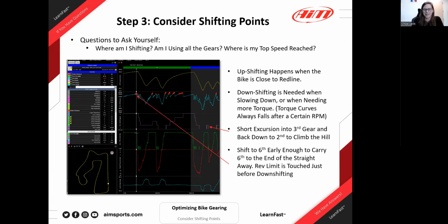And that's a cool preview of where we're going to talk at some point with the math channels. Now RS3 has the ability to have lookup tables. So I use the lookup tables, and the lookup tables know which gear you're in. It actually knows, because of the table that you input, the gear ratio. From knowing the gear ratio and your tire circumference, you can actually calculate the wheel speed, or the theoretical wheel speed.